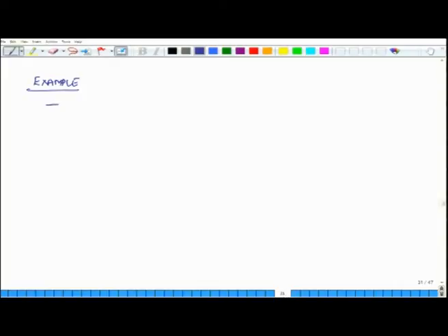So, the example we are going to say is that sigma Lu is 500, sigma Tu is 5, tau LTu is 35, sigma Lu prime is 350, and sigma Tu prime is 75. So, these are the material properties, okay. And theta, for purposes of simplicity, is 45 degrees.